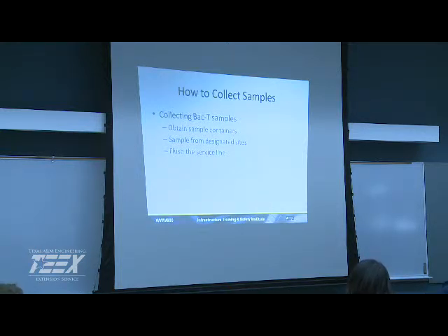Yeah. So you want to look at your methods. A lot of times, especially the older gentlemen in our distribution system, they had the color wheels, and they wouldn't let them go. They'd hide them so people couldn't find them, because if supervisors found them, they're supposed to take them away, so they'd go to the electronic colorimeter. But if you do use the color wheel, make sure it's not old and faded. It's not sitting out in the sun, because it'll change it. There is some discretion in there when you look at it, so you kind of get a ballpark. But I'm a big fan of having instrumentation, knowing that it's calibrated properly, and then getting good results and having confidence in that data.